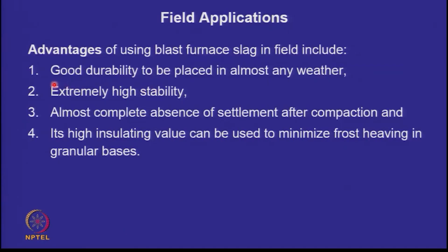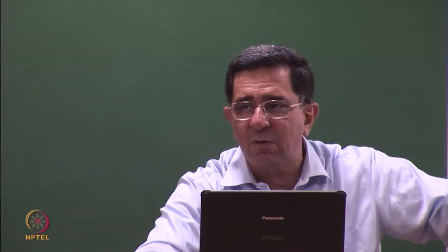And the advantage is that it can be placed in any weather. That means it's not like clay, which becomes slushy. In wet weather you can't put clay, but if you're compacting sand in wet weather, no problem. Rain comes, go and work, after 15 minutes the water would have gone away, your equipment can move. If you have clay, rain comes, please wait for a day till the site dries up before your equipment can go. So you can work in any weather.